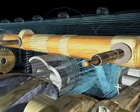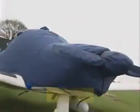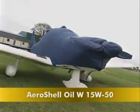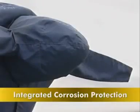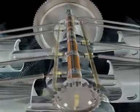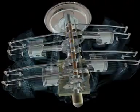When an engine is stopped, oil gradually drains to the bottom and continues to do so as the unit remains idle. If an engine remains unused for long periods, then corrosion can become a serious issue. Products such as Aeroshell Oil W15W50 or Aeroshell Oil W100 Plus are designed to address the problem, as both contain a corrosion inhibitor. The speed at which oil will circulate when an engine starts is significant in the prevention of damage. This means that the correct oil needs to be selected for the aircraft's operational climate.